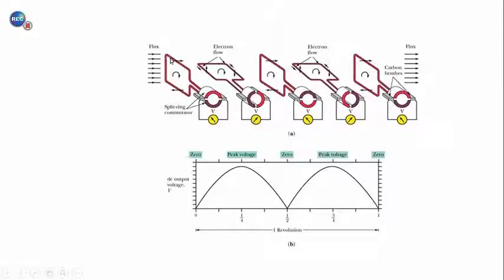And so this part of the conductor is connected to this lighter red colored part of the commutator, and this bottom part of the conductor is connected to this purplish color of the commutator. And the two parts of the commutator do not touch one another. They are insulated from one another, and current cannot flow there. But the commutator does rotate with the conductor, and as the commutator is rotating, these brushes are riding on the commutator.